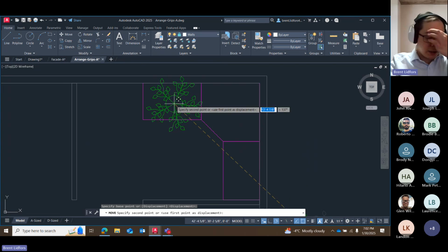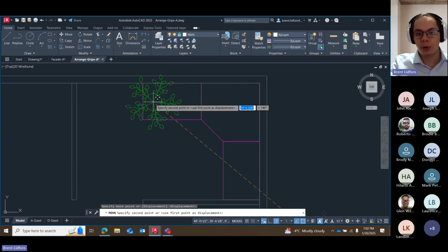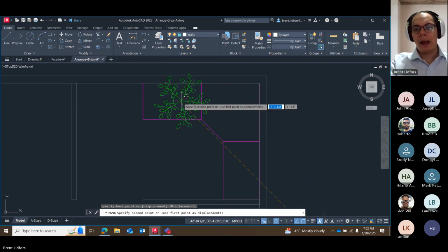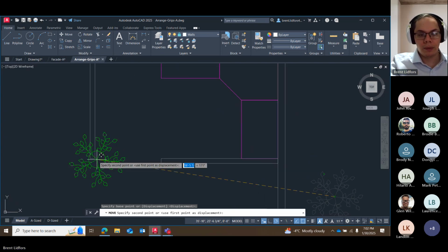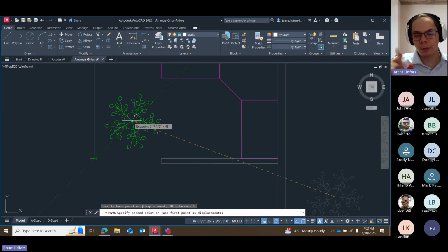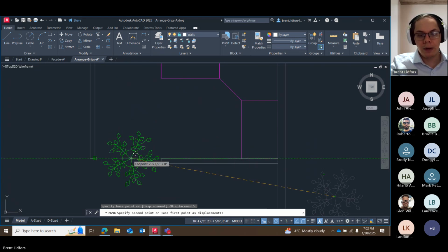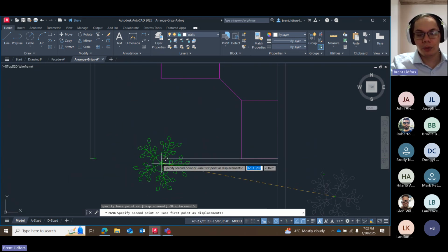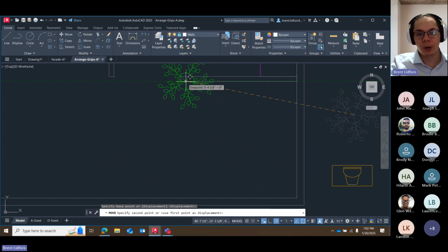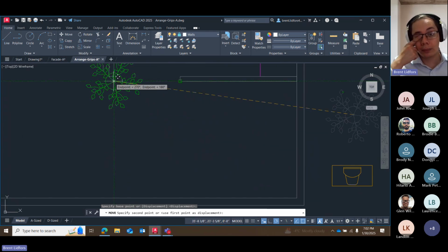Then I can highlight both the midpoints, the upper and lower part of the desk, as well as the left and right. And with object snap tracking, you can use 1 point. If I hover over it and move away, it leaves a little green plus sign for a tracking line. But if I use 2 points, so if I highlight a second point just by hovering over it and moving away again, I can get 2 tracking lines.